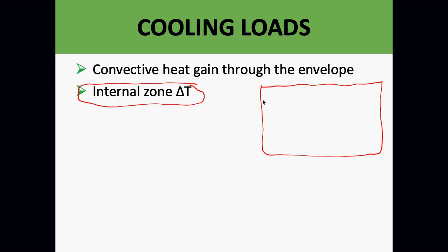The reason we worry about this in a big commercial building is if this wall here is south-facing, and this wall here is north-facing, and I have a relatively large building, my south-facing side of the building, the rooms over on this side, are going to heat up much hotter than the rooms on the north side of the building.